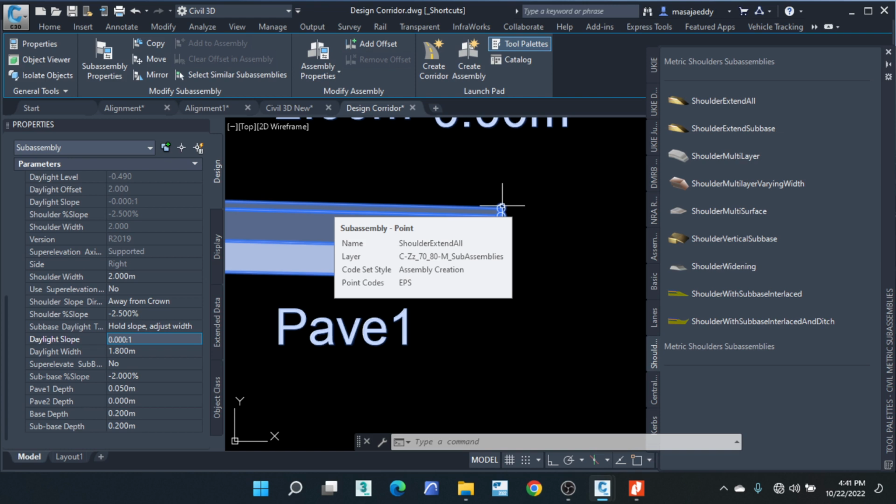Now that is the drawing we are using. Is it possible that you can shortcut the surface that you already shortcut from? You have to go back to the original drawing. If you have already created a data shortcut for the surface, you just have to link the new drawing to the shortcuts folder. You can still get the surface into the new drawing.